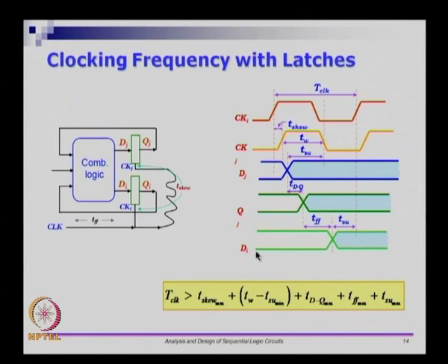We want to ensure that there is this chain of events, right, Dj to Qj to Di, we want to control all of that. That is why we have done it in this way. So any change in Dj may actually go back and change Di within the same clock pulse, right? And in fact a change in Di could go through Qi and go back and change Dj also in the worst case, right. So several of these events can happen before this latch closes, right. So what this relationship is capturing is from the opening edge of the latch till the close edge of the latch, what is the relationship.